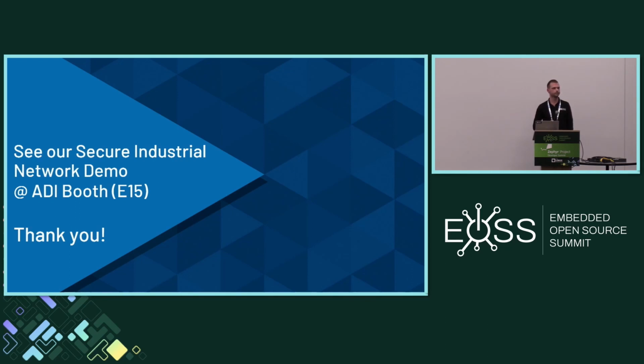Yeah, I was curious. A very good presentation, and I agree that single pair Ethernet is going to have a big play in many of these embedded markets. You talked about real-time and industrial. I'm curious how you see, in the software stack, TSN is a big part of those stacks. How do you see Zephyr's support for TSN in there? I mean, TCP/IP is not exactly real-time, so I'm curious what your experience there is, and if there's more development needed in that area.